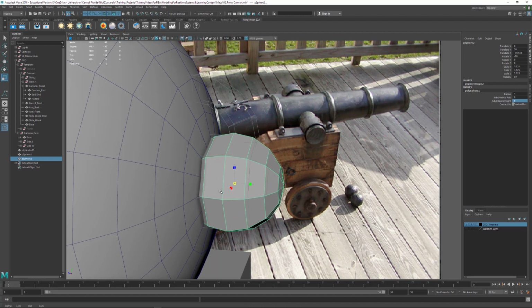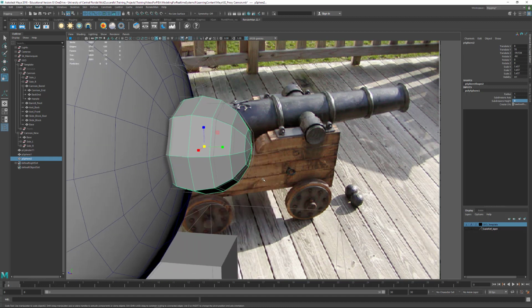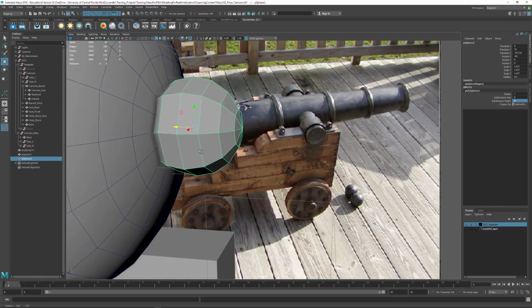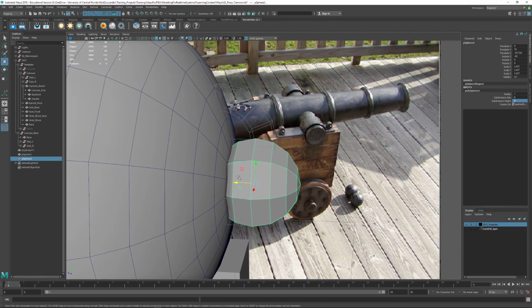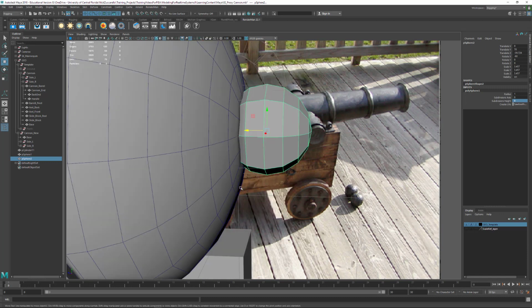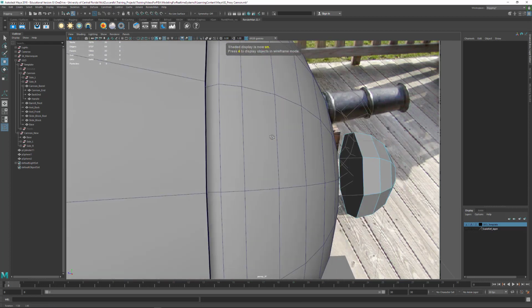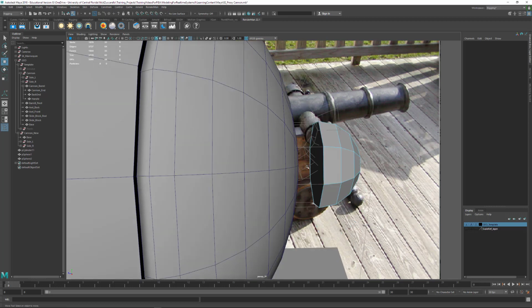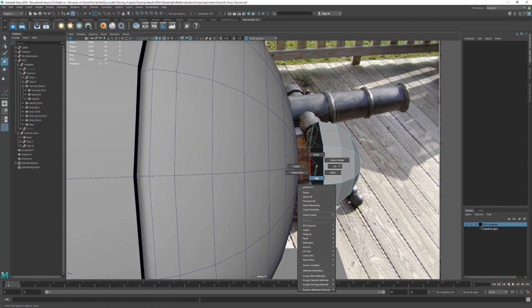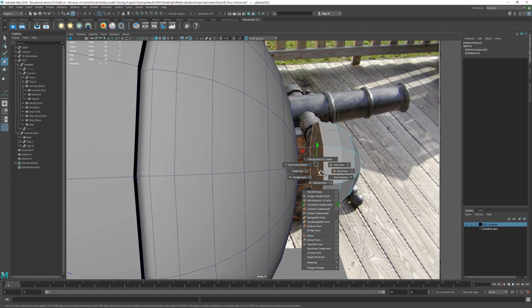So I'm going to manipulate this thing, move it like this. Because I want this thing to be nice and flat, I'll select all the edges for this, hit F10, and drag and marquee on all these. I'll tap 4 to take a look through the model. And I can just hit backspace like this, and it'll get rid of all those edges that were past that certain spot. Now if we right click and say face, we can select a face, and we can shift right click and extrude the face.